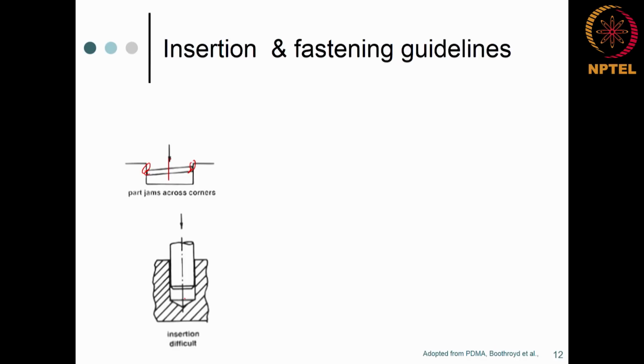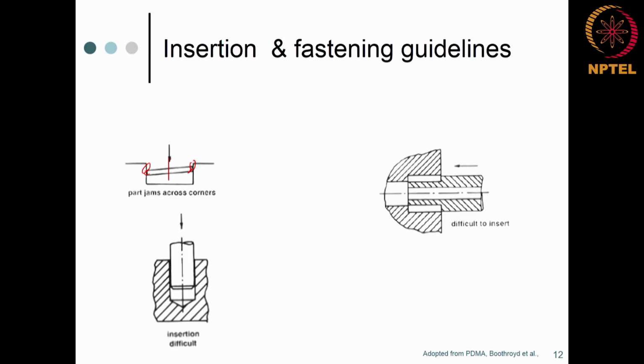So what could be a solution? That is too much. Every hole that you try to screw, you go and apply a vacuum. It's not like so much air, right? It's only this particular space. So you just need some space for this guy to squeeze in. So what you do is you put a hole in the screw itself. There are several screws that have a hole. Well-made screws will have those holes because it's not easy to put a hole in the threaded screw, and those screws are naturally more expensive than the regular screws that you look at.